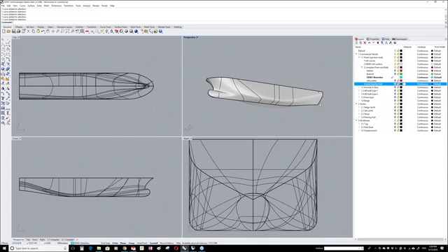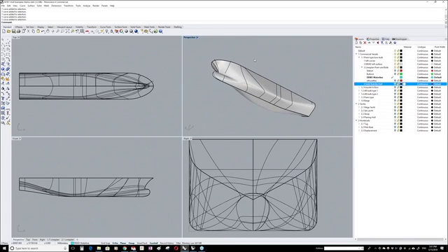But what we normally say is, at least from the midship, you need one aft curve and maybe one in between. And here in the front ship, you see the midship, and you see that we use a bit more, 2 or sometimes 3 in between curves, but not more than that. There's a limit. It depends a bit on the ship type, and that's something you learn more when you go more deeply into the training.